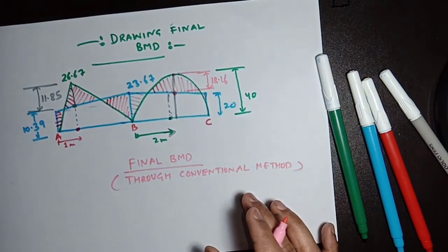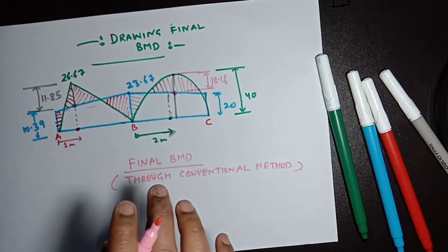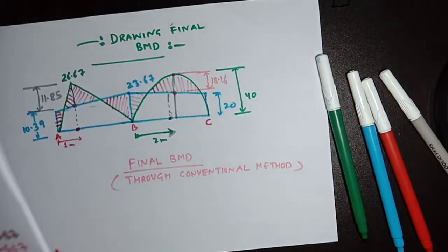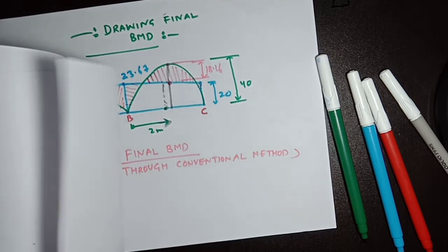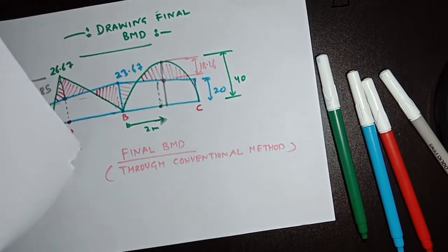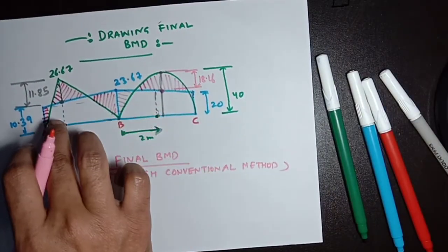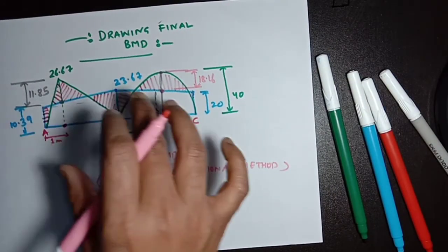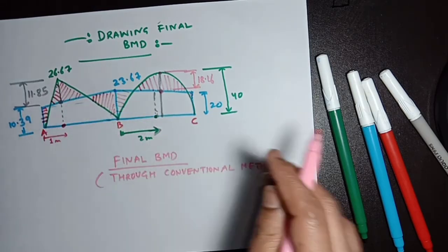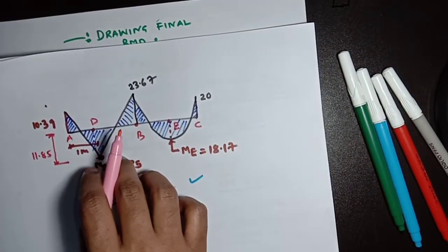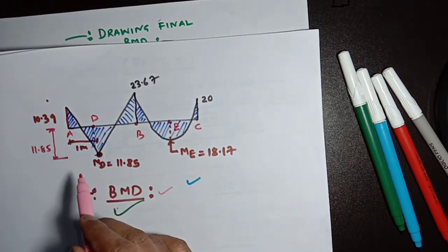You can see the same calculated values which I have drawn through the loading diagram. You will find the same value of bending moment, span moment, or you can say support moment. This is the bending moment diagram which was drawn. This is the superimposition of span moment and support moment. Then after superimposing the two, we have shaded out the final bending moment diagram. But here we can directly draw the bending moment with a loading diagram. The value calculated is here.